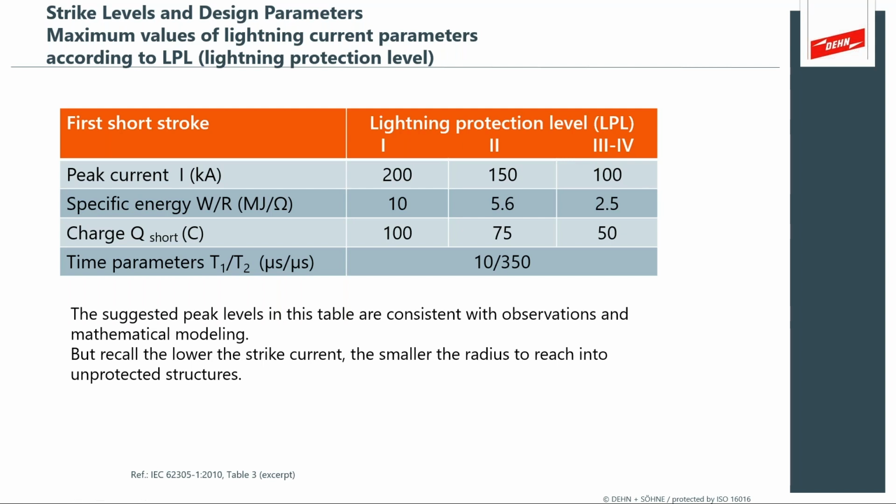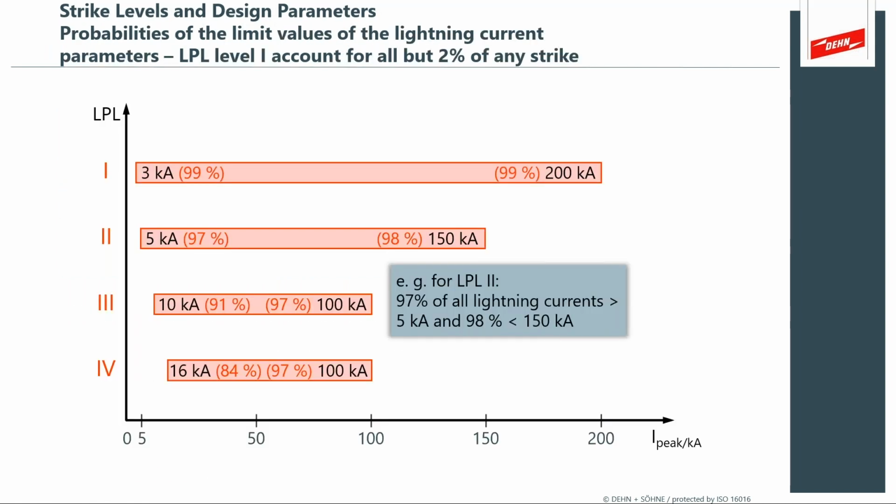And in NFPA methods, they understand, and it's fairly well represented, that the energy is then divided. So some of it goes direct to earth, some of it propagates backwards, and you can see that in the methods. But these are the parameters that are used to describe lightning, and from this we get what are described as the peak and the lowest level. Not all lightning is created the same.